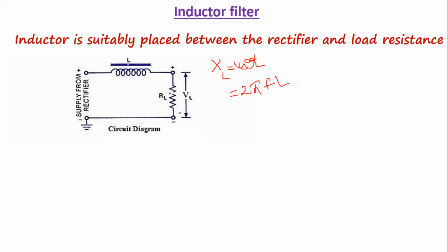So you understood how the AC is filtered out, and finally you get the DC component only across the load. Still, lower frequency components of AC will be transferred a little through the inductance coil, but higher frequency components will be blocked.